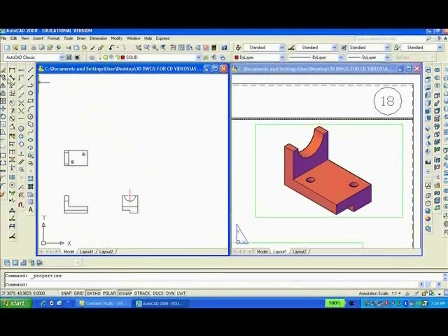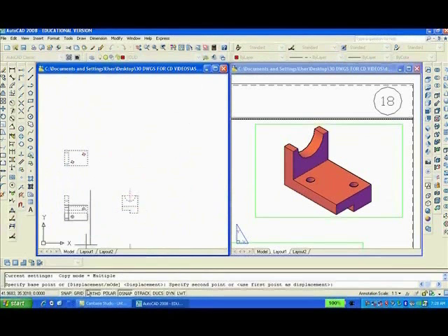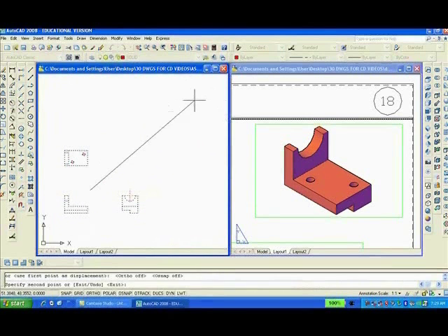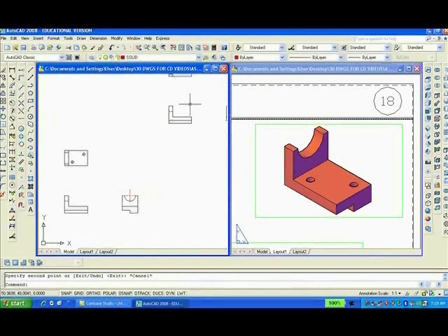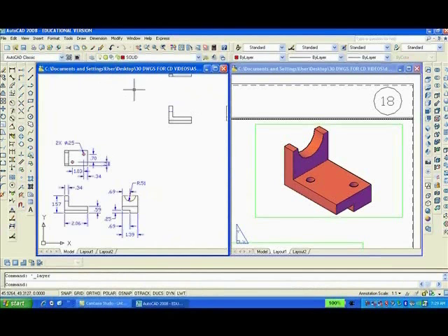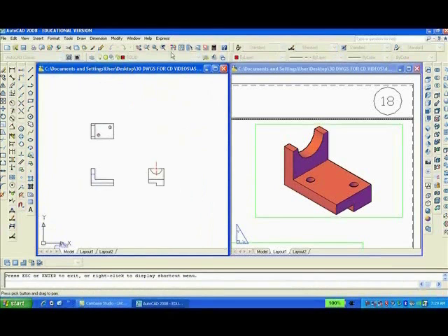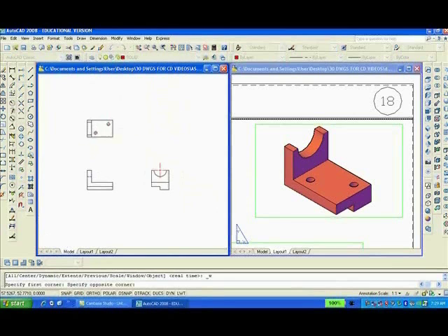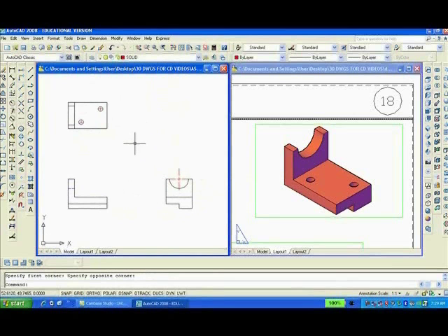So I'll go to Copy, then move them to the upper right with Ortho and O-Snap off, like that. And then I can thaw the dimension layer. And now, as usual, we're going to pan and then zoom to enlarge. So what I need for the solid model, I'll start to use.